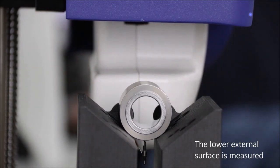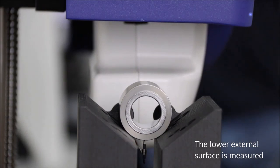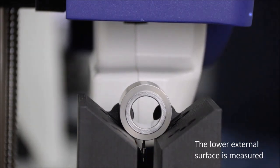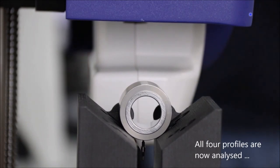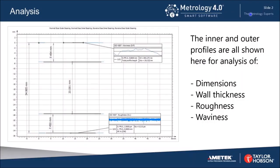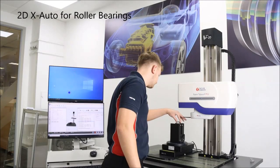Note that we're moving the column down each time to move to the bearing. So the gauge is pretty well close to its 0 position for each of its measurements. And here are the results. We can see the various diameters, the internal diameter, the external diameters, and the wall thickness is shown here as well. We've also shown roughness and waviness alongside it.